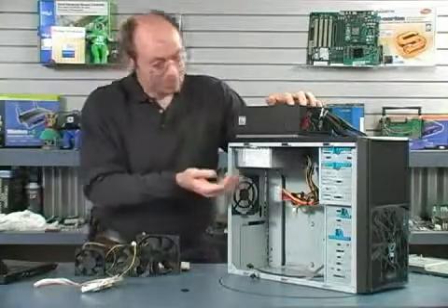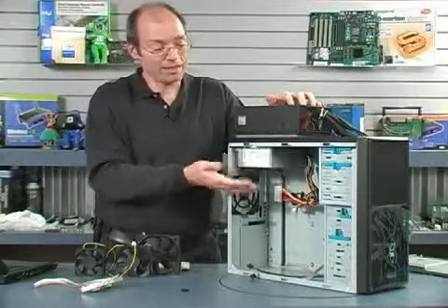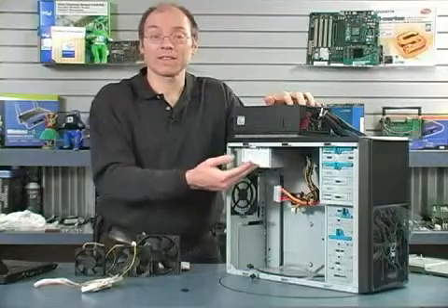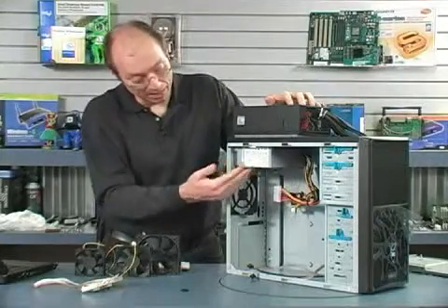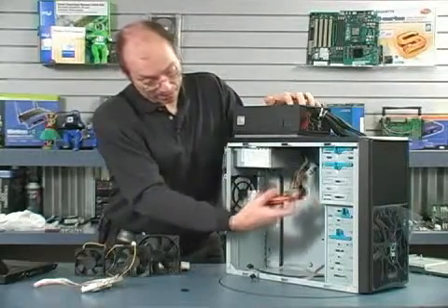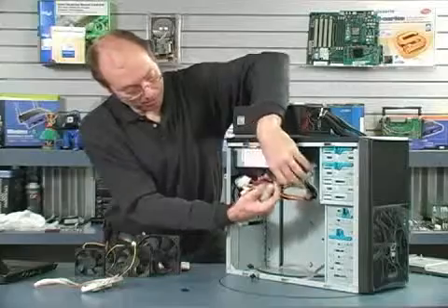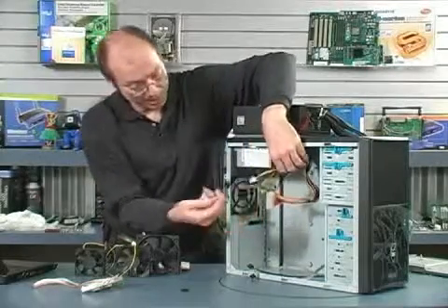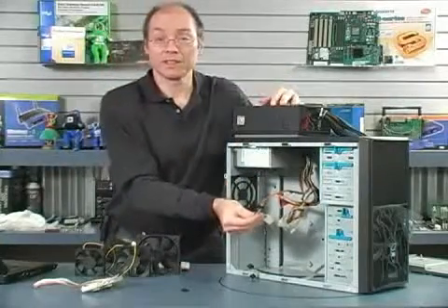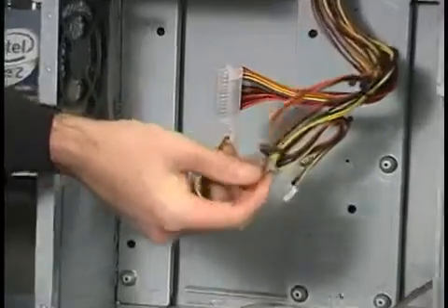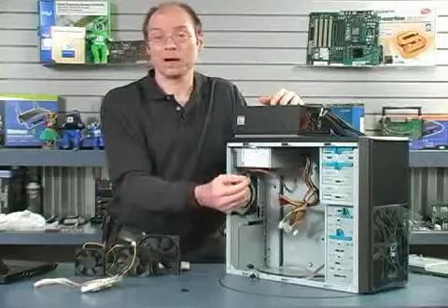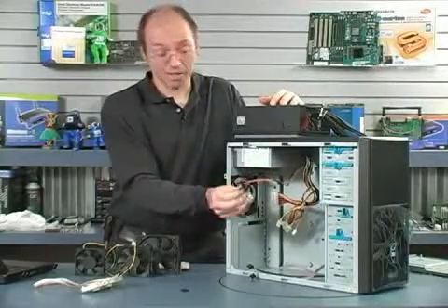Well, generally when you buy a case like this, I believe it costs like $50 or $60. The power supply that comes with a case like this, if it does come with one, is usually not necessarily the best type of power supply. For example, I'll note a couple problems with this one. This power supply that came with this case has literally one SATA serial ATA drive power connector. Now I plan on installing 4 hard drives in this case, and I could fit 6. I'm not going to be able to power 4 or 6 hard drives with a single connector like this.